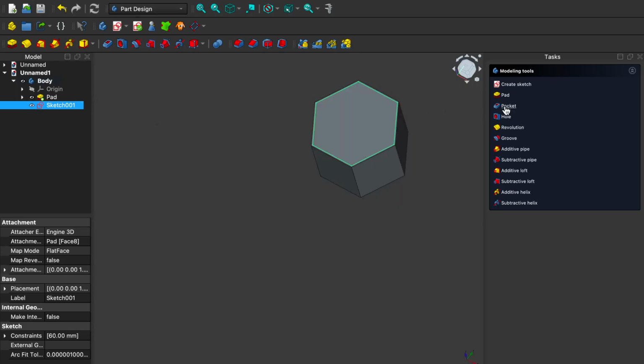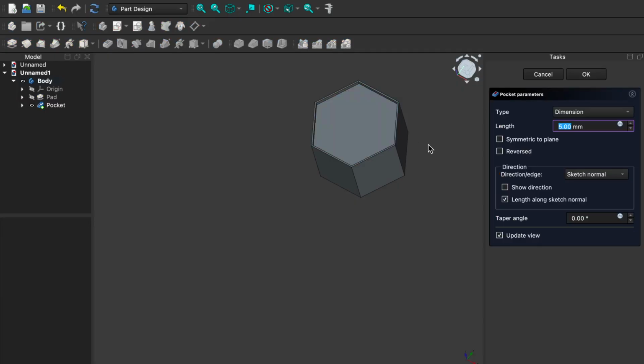the surface. So you're going to click on the pocket right here, or you can use this one, whatever feels best to you. See, this asks me how far I want to go. If we recall, the height of the beginning shape was 80, so I want the bottom thickness to be, let's say, 3 millimeters. So I'm going to subtract 3 from 80, which is 77. Yeah, plus 3, that's 80. Okay, that's the right one.